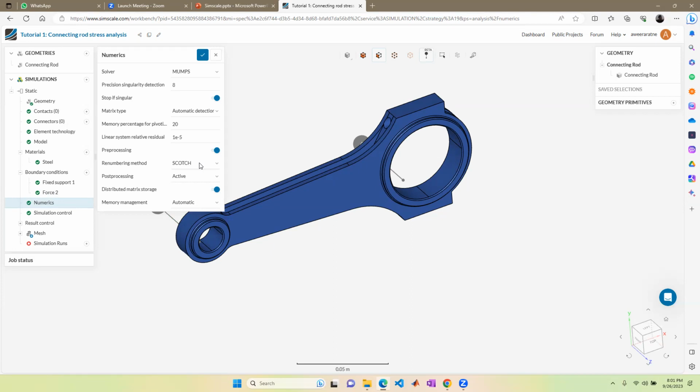If the final year students remember, even in MathWorks, we set the solver settings to auto, which is quite different from keeping it at the default settings. If you set it to auto in MathWorks or Simulink and Simscape software, that software will figure out what the best solver setting is for the model that we have developed and run the solver at its optimal settings.